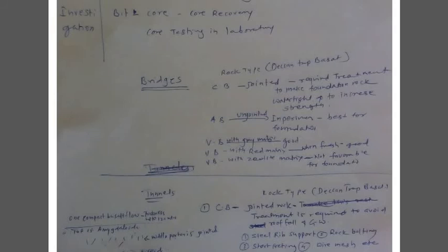Then the drill hole data will be available for interpretation. Then construct a geological section throughout the length of the tunnel. Mark discontinuities, joints, fractures, faults, water loss and water gain. So this is about the preliminary geological investigation as far as tunneling is concerned.